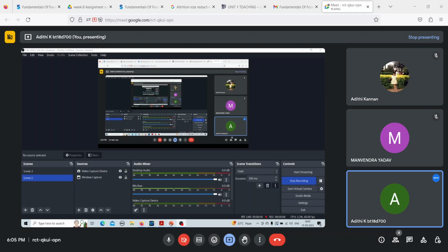So Es, the surface energy per unit area, into area will give you the surface energy created by crushing, divided by Wn, which is the energy absorbed by unit mass, is equal to eta C, which is the crushing efficiency. And generally what happens is that the majority of the energy that is absorbed by the solid will not be converted into surface energy by crushing.